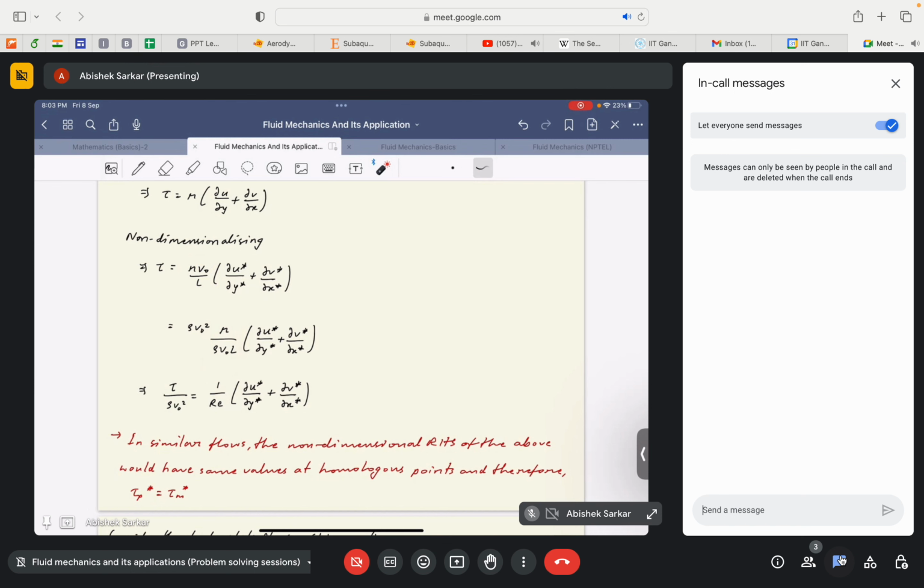That's helpful for us because we can directly deal with the Reynolds number as an independent parameter rather than dealing with mu, rho, v naught and L separately. All these four parameters can be reduced to a single non-dimensional parameter that can be varied to understand the flow physics.